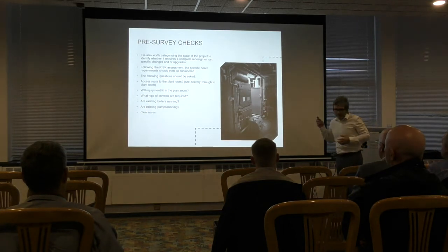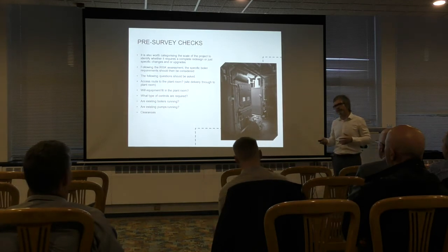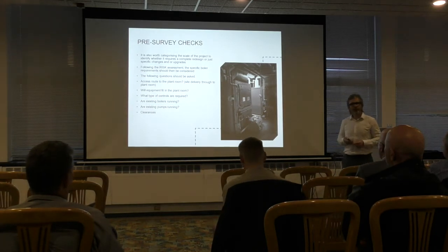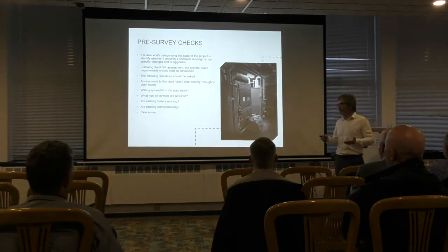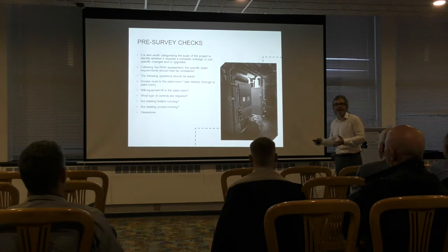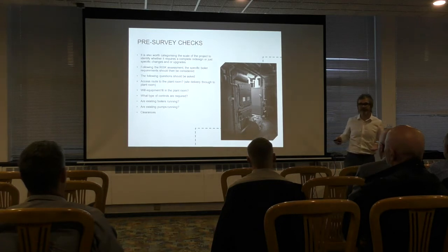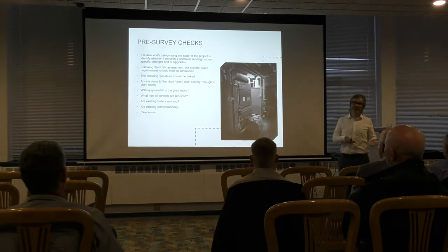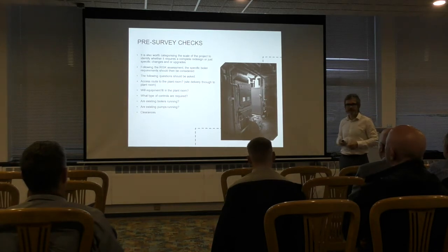But also, when changing the boilers you have to try and keep heat on as well, because more often than not, the building occupiers and owners want their boilers replaced. They want brand new boilers in there, but they don't want to compromise any heating or hot water whilst you're doing so. And that can throw up all sorts of challenges. It happens often where we've got to replace those boilers, but we've got to keep the heating on. So it's about how you go through the process of that replacement.